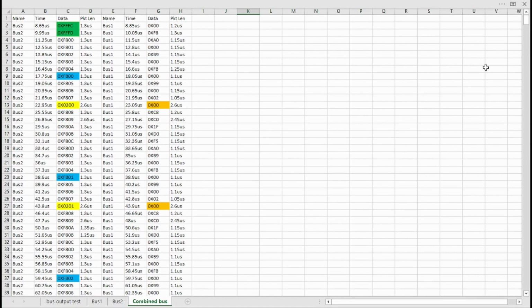Okay, so this Excel file is the output from the logic analyzer. Now, I've had to play around with this file a fair bit because the data packets for the address lines were much neater than the data lines. You'll remember there were a few bits in the early part of the data where the ROM file had to settle down to output the correct data. So I've had to throw away some of those parts and just match them up, which isn't a massive problem, but it's just a bit of extra work compared to the slow version where it all lines up really well.